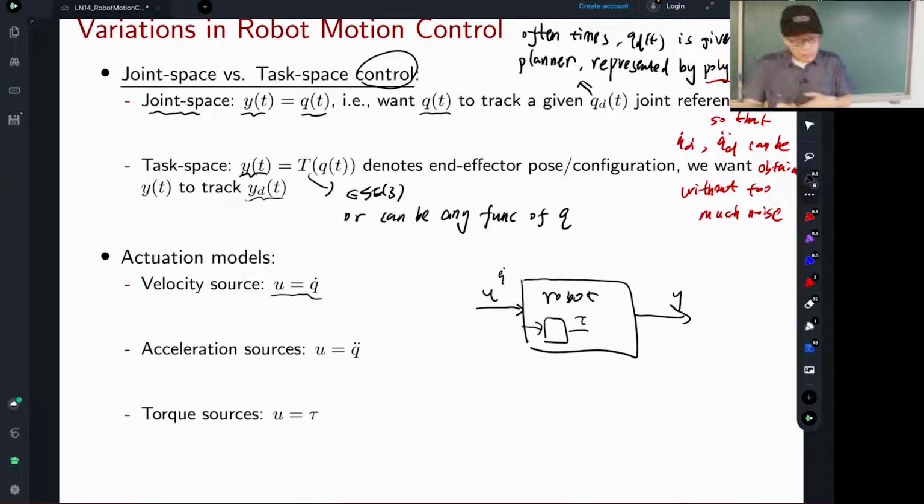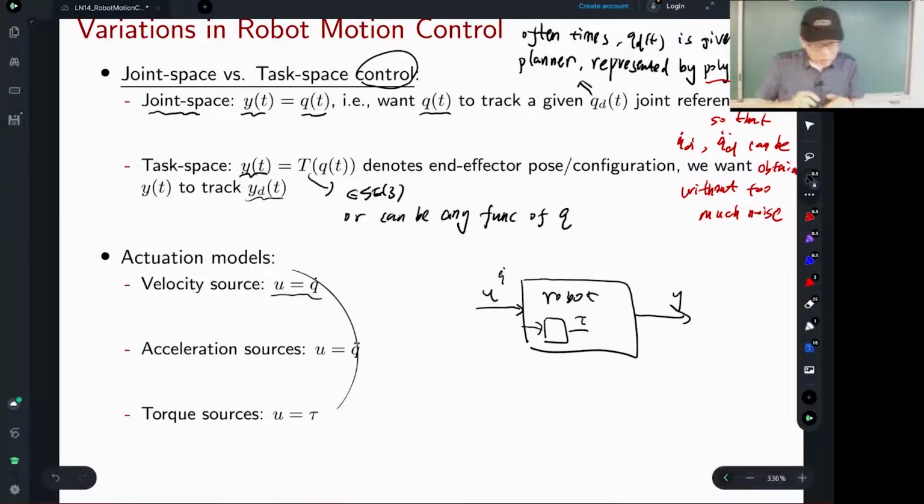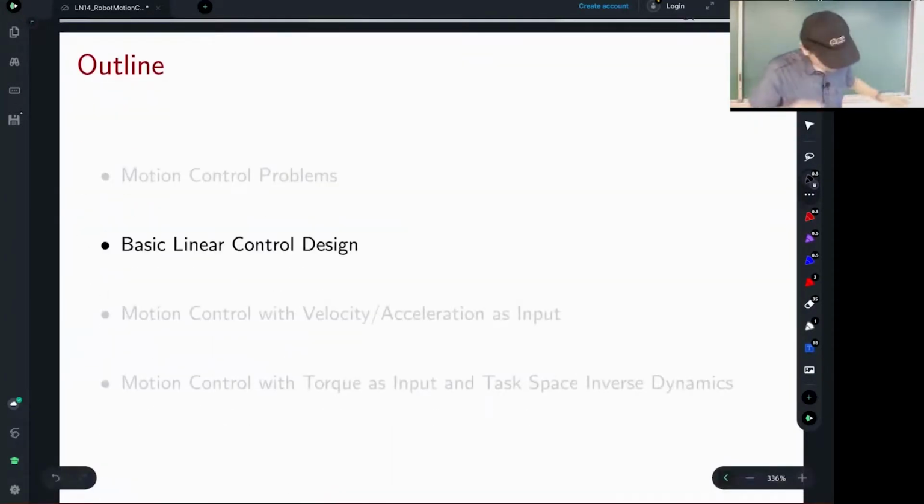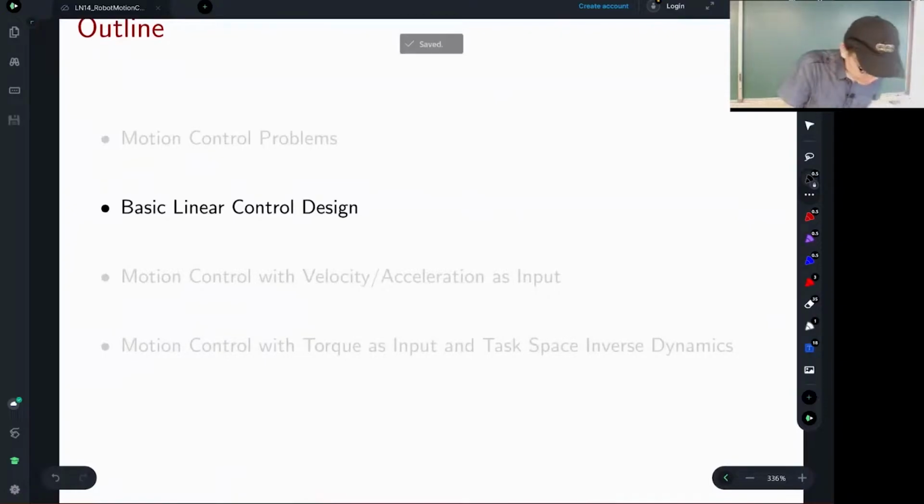But in our design and analysis, the lowest level is velocity control, that I emphasize. If you don't allow me to do the velocity directly, then I can specify velocity control, assume it, then integrate to generate the desired position. That's your assumption, right? You need to make sure your assumption adapts to the application scenario. I think that will be clear after we see some examples, okay?